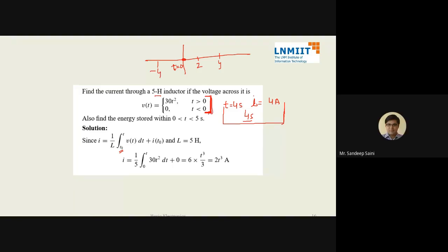Another reason from the circuit point of view is, if I have no information about a particular time and I have to assume, if I assume 0, there is a solid ground to say that no power source was attached to the circuit, no voltage source, no current source. So it will have 0 voltage, 0 current. How can I assume that there was 5 volt or 5 ampere current flowing? That justification will be very difficult to defend. But if we have to assume, then assume 0.